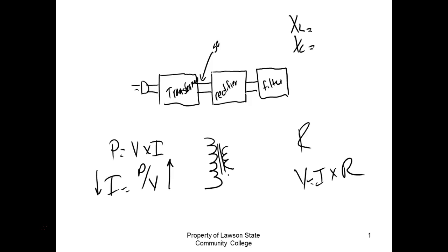So we keep stepping it down. The closer we get it to ground, and the closer it gets to us, we keep stepping it down till it gets to our house. And we have 2 voltages at our house: 120 and 240. All your high wattage loads run off 240. They are designed to run off 240. All your lower wattage devices run off 120.